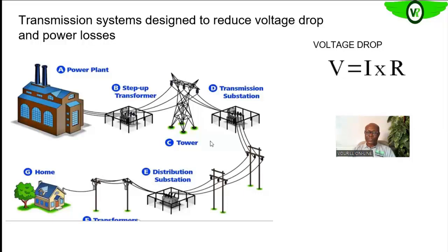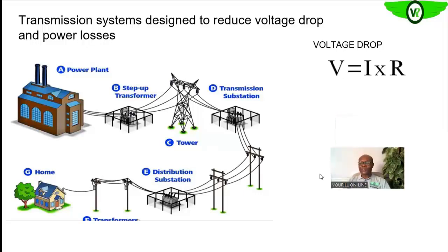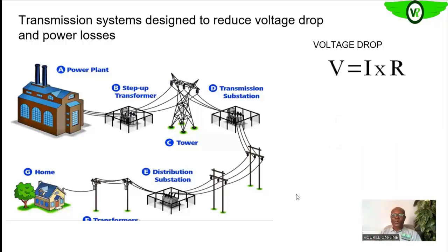So these copper conductors all have some level of resistance. Once the power is on, that is, there is load on the line, some level of current will be flowing on the line. And that current, as it flows through the line, definitely, since we have some resistance on the line, will cause some voltage drop from that Ohm's law, V equals IR.